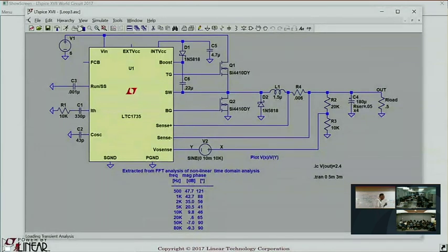Now, you'll end up with a couple things you have to be concerned about. One is that it's correct in practice, but it's not exact academically. So far I've gone around the feedback loop twice. First time I said it's two poles and some delay. I said, oh no, that's not true. It's actually two poles and some zeros and no delay. In practice you can run with that. That's good. That's the way power supplies actually work. They're actually two poles and two zeros and no delay. That's the way they actually work, all of them. But it's not exactly correct.